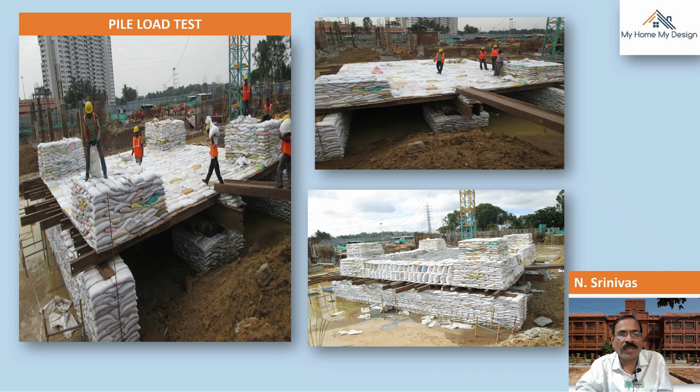The systematic arrangement of ISMB girders, placing over sand gunny bags, the number of bags has to be piled like this. Then the load is applied over it and recorded probably for 24 hours or 48 hours. Every 30 minutes the readings have to be taken, how much load is coming over the pile, how much deflection is allowed, what are the standard permissible limits. Everything can be determined with the help of this test, which is called the pile load test.